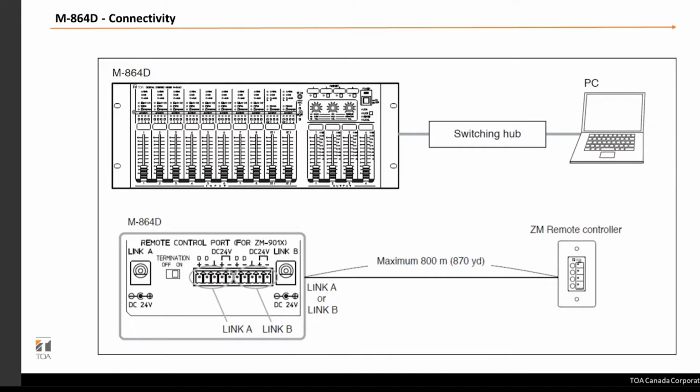Over the years, we did have some people utilizing non-shielded cable, and some problems were occurring with non-shielded category cable, Cat5 or more. I mean, it's not important to use really the latest category cable, but it has to be shielded.